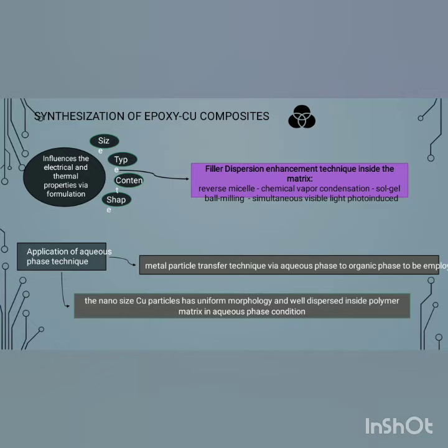However, in the application of the epoxy Cu composite, it is advisable to use the aqueous phase technique. This gives the opportunity for the metal particles to be transferred from the aqueous phase to the organic phase. This is because the nano-sized Cu particles have uniform morphology and are well dispersed inside the polymer matrix in aqueous phase condition, referring to Muhammad Hamizi in 2012. Those are the procedures for the aqueous phase technique.